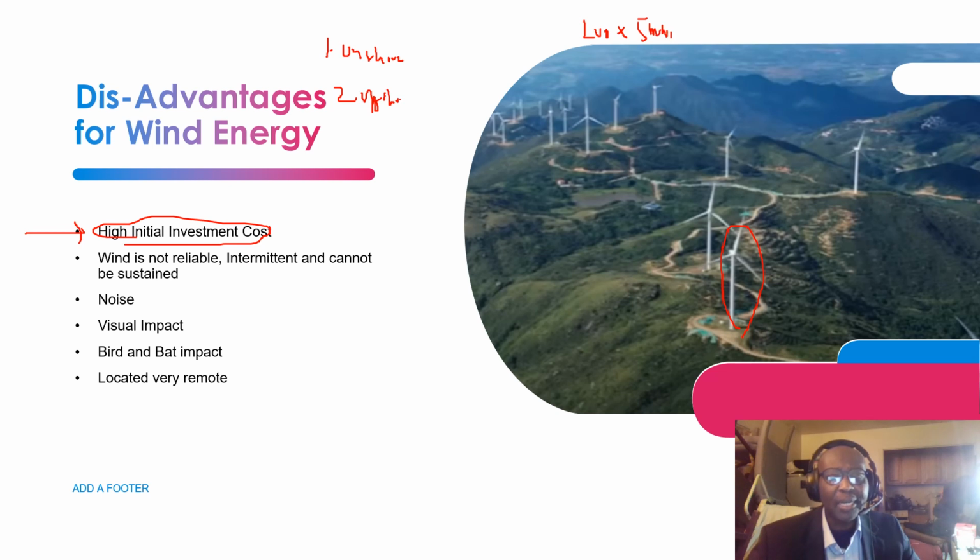I think quite recently they came up with one that was about 6 point something megawatts, right? But let's put it at 5 megawatts as the maximum wind turbine rating for an onshore facility. But for offshore, currently it is at 15 megawatts. And what is the reason? Because offshore you have a larger spacing, larger area, and the size of the wind turbine, and all the noise that it creates and the blading and all this, the offshore facility right out far in the ocean, it doesn't disturb anybody.